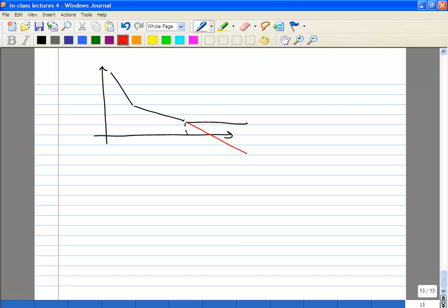Okay, and what you will see is typically, if you don't have any other circuits, that is probably what will happen, because your tank is actually going to have a response which is 1 over delta omega squared forever, or at least till a point where the small signal approximation is not valid anymore. Okay, so that is one thing which hurts you.